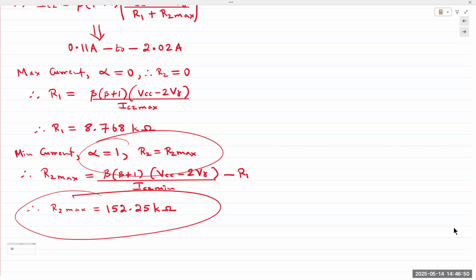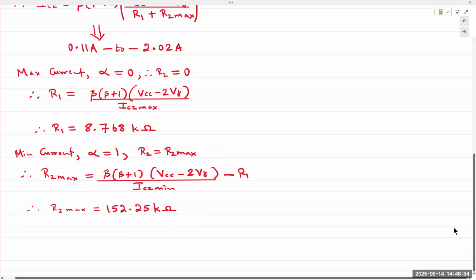What this allows us to do is multiply the gain by the thousands. So in this kind of transistor configuration, the beta of the transistors is multiplied because the output of the first transistor is fed as input into the second. So the first one is a beta of 100 and the second one is a beta of 100. The overall beta of that configuration would be 10,000. Okay, so it's amplifying the current to a very large number.